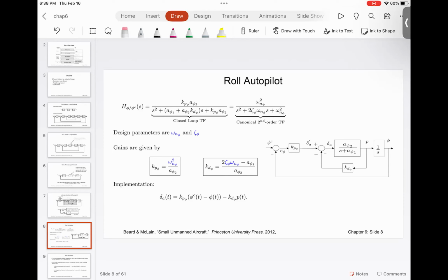Any questions? This is very practical, because when I worked on the Bell 609, as I said, a tiltrotor, they said we use velocity feedback. I thought, oh wow, this is something like model predictive control. At the end, when I looked at the loops, they were simple PD loops. Usually I have not seen an integrator being used, but typically they use PD loops.